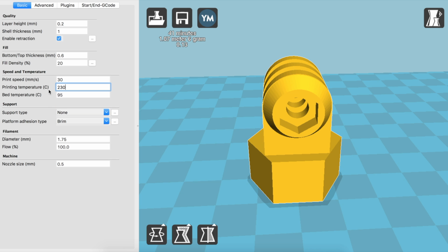Different manufacturers have different tolerances for their temperatures, and they work a little different. So this is just going to have to be something that you experiment with for the brand of material that you use. I find that PLA usually works well for me at 200 degrees. Another thing that temperature is going to factor in is the strength of the layers. So you definitely want to print some calibration cylinders that I'll show you at some other time, and that's going to let you know how well the layers are going to be sticking to each other with the different temperature settings. All right.